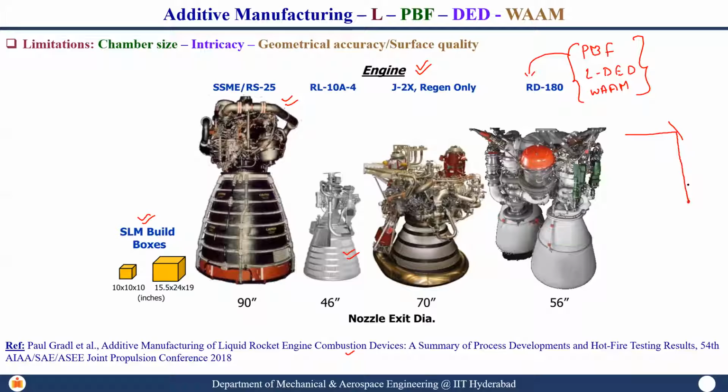Instead of making it fall here, if you make it fall from this point to somewhere here, assuming I made my plate quite large, then the spot diameter we achieve at this point and this point will not be the same. It becomes more elliptical. So the bead characteristics or the deposition characteristics over here and over here don't match. This is something which is limiting the increase in the size of the build volume.